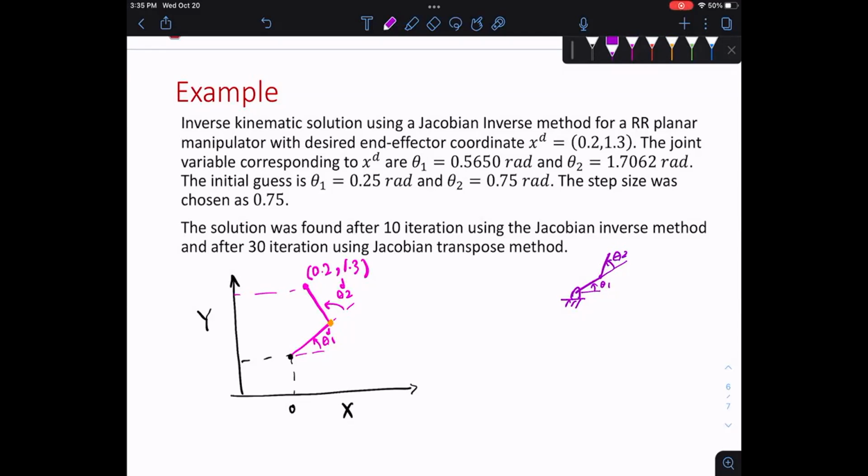You don't want to, let's say, start from an example. Let's say our first guess is going to be something like that, because the lengths of the links are fixed, right? You're going to start from an initial guess. I'm going to call this x0, y0. Let's say x0, y0 is here, which will translate into, so you start from theta 1, 0, and theta 2, 0, right? You say that, let's say my first theta is at 30 degrees, my second is at 45. Let's see where it ends up. You put in your forward kinematics, you'll get x0 and y0. You compare, you see that you're not there.